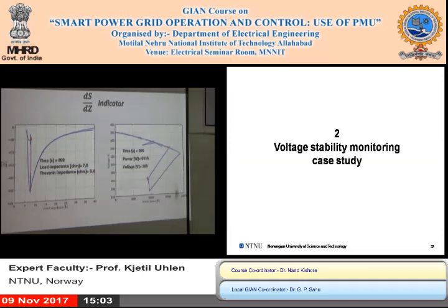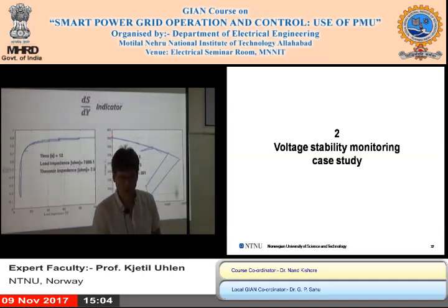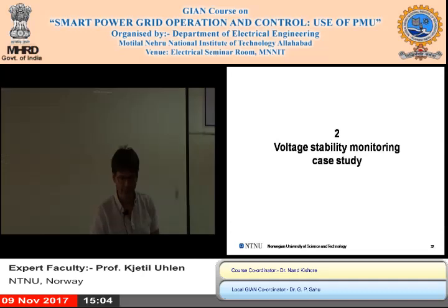And you see it's now on another PV curve, you might say, because this is the post-contingency situation. You see now it's very close to instability. But then it goes back, it connects this again, so we have higher impedance. No, I mean less impedance. This is a parallel. And then it follows the original line. And that's the same with the others, but we don't have time.